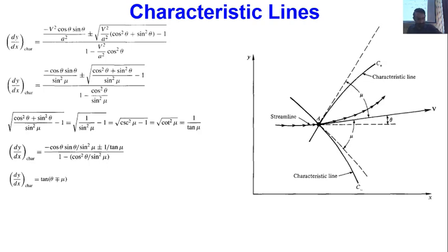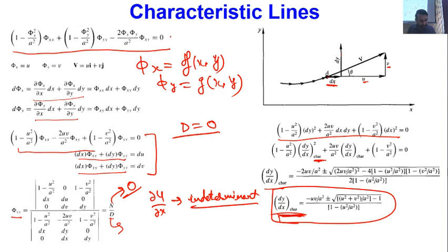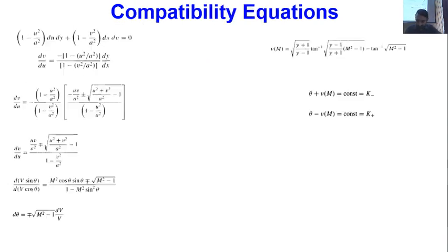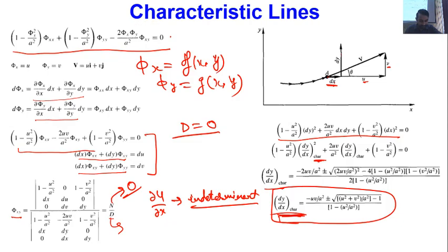Okay, so before that let's also try to see. One important point is, inside this square root I have u square plus v square by a square minus 1. What is u square plus v square? That is nothing but the total velocity v square, so v square by a square minus 1 is m square minus 1. So the square root of m square minus 1 is coming.